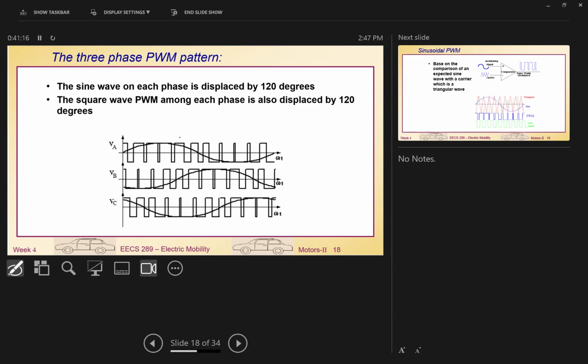What that means is, if you go by the basic equation i = C dV/dt, consider your motor winding. You have many turns of copper winding, which they call enamel copper winding. Between the windings, there is an enamel coating to insulate each winding from the others.